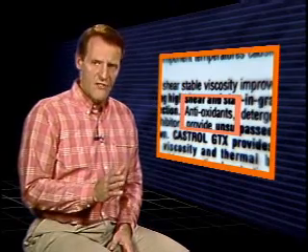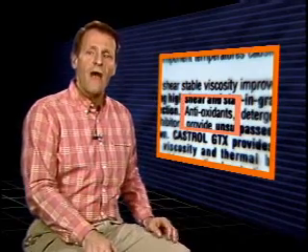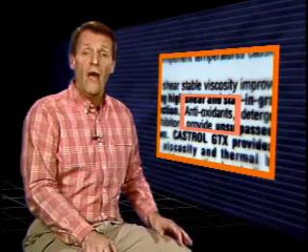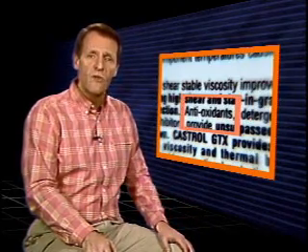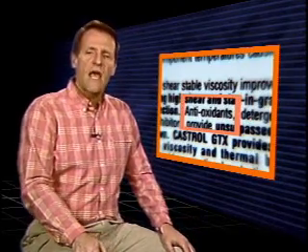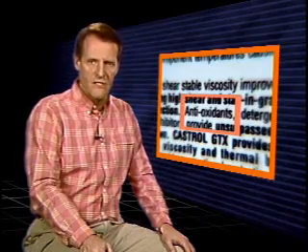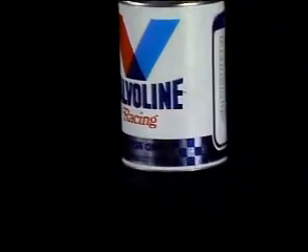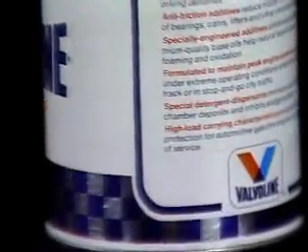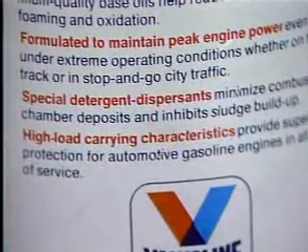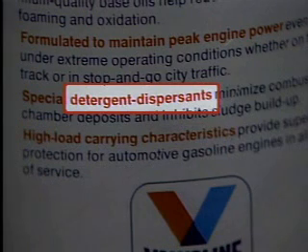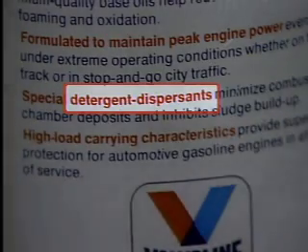To help control oxidation, additives called oxidation inhibitors or antioxidants are blended with many lubricants. These additives greatly reduce the rate at which oxygen combines with lubricants. And to reduce the formation of carbon deposits in sludge, chemical additives called detergents and dispersants are added to many oils and greases. These additives keep particles in the lubricant suspended so that deposits in sludge don't form.